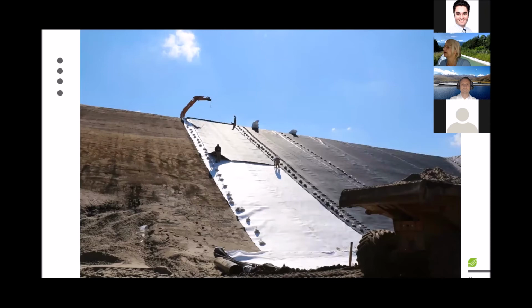This picture shows the installation on the slope, and as addressed at the beginning, the protection layer has to be sufficient to cope with the situation of the subsoil. So it should not be that I choose the cheapest one, and later on I see that I have puncturing of my geomembrane, considering that the geomembrane just on top of the slope can be relatively weak at high temperatures. Joints on slopes should be avoided, so the lowest amount of joints should be established. So geomembranes could be manufactured in lengths like the slopes. Laying flat, as addressed, is a key in these applications.